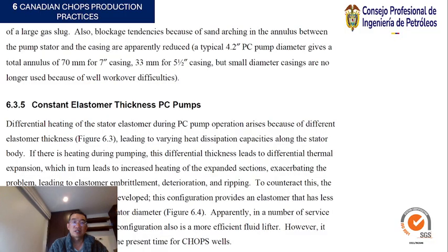6.3.5 Constant elastomer thickness PC pumps. Differential heating of the stator elastomer during PC pump operation arises because of different elemental elastomer thickness, leading to varying heat dissipation capacities along the stator body.